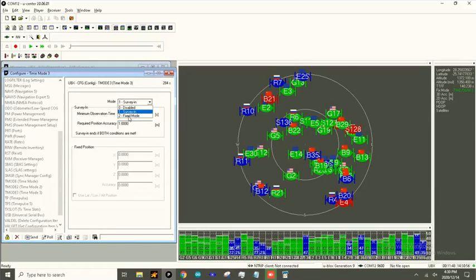So if you go back into the configuration window, again to TMODE3, we can select the fixed mode, and then we'll enter the coordinates over here. This will be explained in a bit more detail in the second video, as there are additional message options that must be changed or enabled for the RTK functionality to work correctly, together with the provided coordinates,